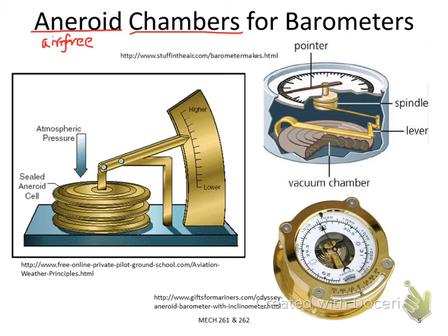You also may wonder what is the purpose of measuring atmosphere pressure. I think I have told you some examples before. For instance, we care about weather, and in a lot of weather forecasting models, one of the important input parameters is the atmosphere pressure. When weather changes, you have a relatively higher or lower atmosphere pressure. So atmosphere pressure measurement is useful for weather forecasting, and it can also be used to measure altitude. This is actually an altimeter.